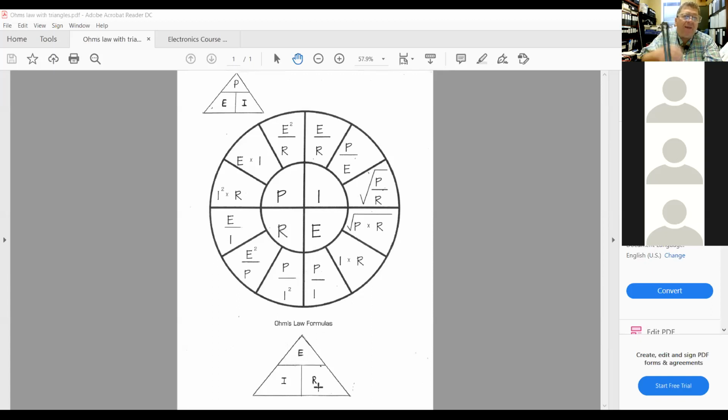So what do you come up with now? What does E equal? E equals your voltage. Okay, which is 240 volts. Okay, and then what's I? I would be 14.58 amps. That's right. Now, so how many ohms should we have? 16.46.